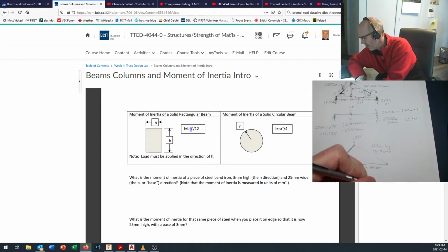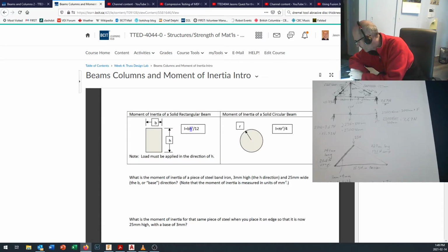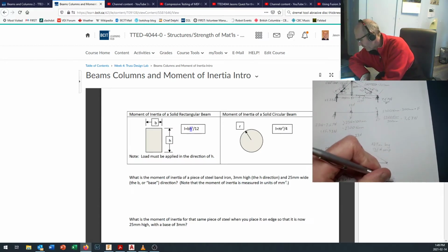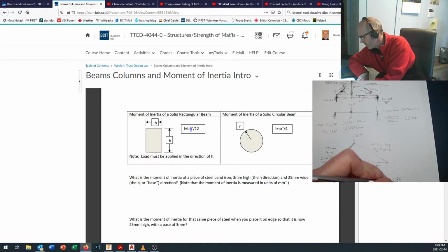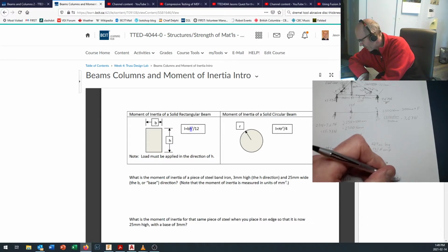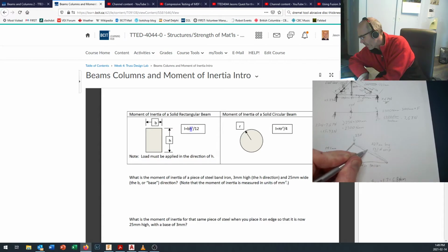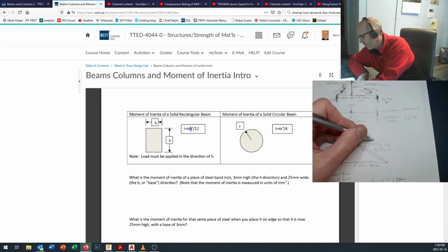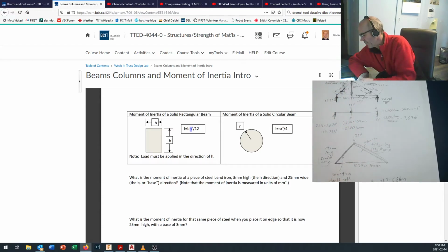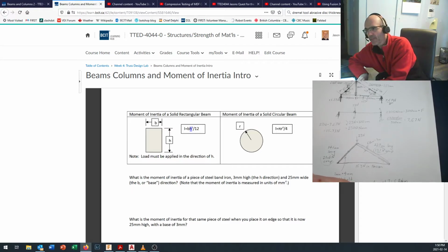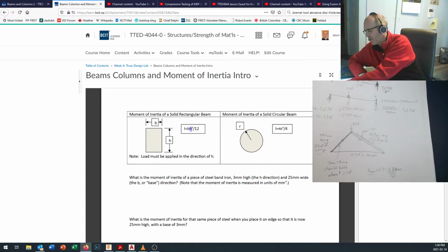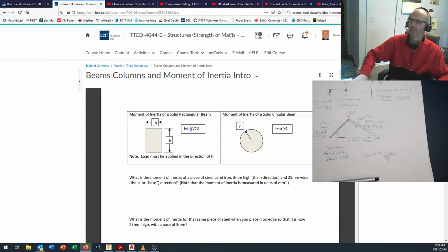So I came in here and I said 4 millimeters times 1.7 equals, I think that came out to be 6.8 millimeters. We'll get back to newtons in just a moment. And I said, okay, right in here, I'll cut this out and I'll make this 6.8 millimeters by 3 millimeters. And that should hold 17 newtons because a 3 millimeter by 4 millimeter piece should hold 10 newtons. So if I bump that width up by a factor of 70%, then my overall structure should be 70% stronger.